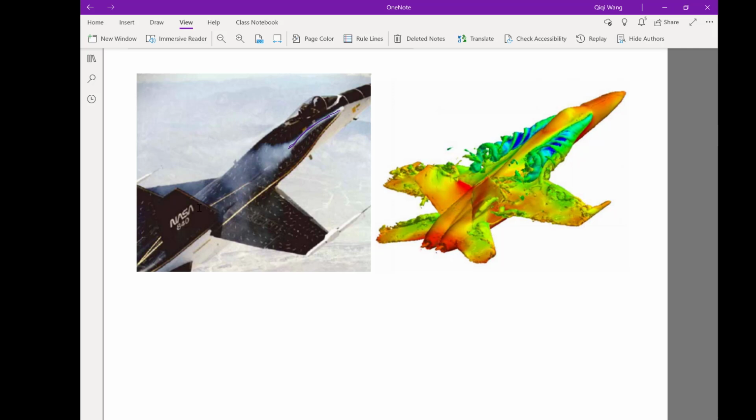What we do in this case is we have to discretize the entire space outside the airplane. Okay, we have to mesh the outside of the airplane with a mesh. Discretize the space with many millions of grid points. And the partial differential equation is going to be approximated by an ordinary differential equation with, in this case, 5 variables, 5 states, 5 numbers on each grid point. So if you have a grid of, for example, 40 million grid points, and you have 5 numbers on every grid point, it becomes a 200 million dimensional state variable. So you have 200 million coupled ordinary differential equations, right?